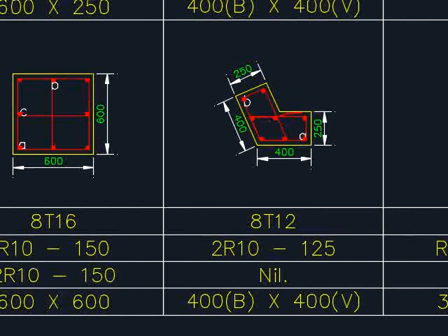However, based on the pathway of your link, you will require an additional 2 reinforcement bars. Let's make this column have a minimum of 8 units of reinforcement bar. This is one of the considerations.